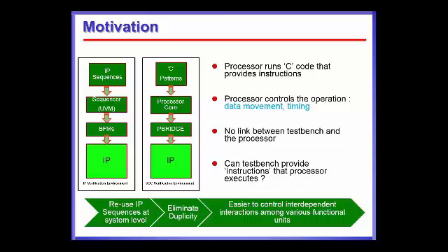Then we thought, can the test bench provide instructions that the processor can execute? Because through those C programs, what we are actually telling our processor is that these are a bunch of instructions, you go and execute them. So if those instructions can be provided by the test bench while we do SoC or system verification with a processor, that would pretty much solve the problem that we had.